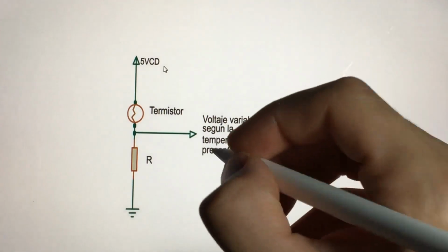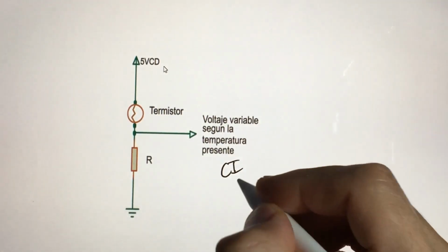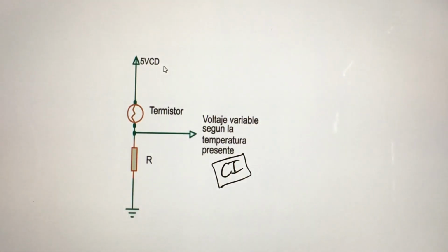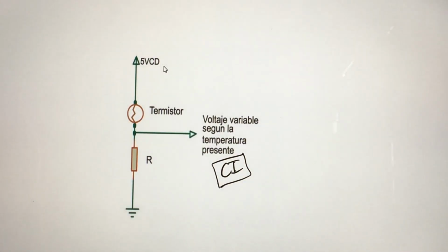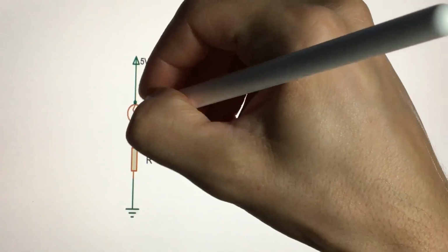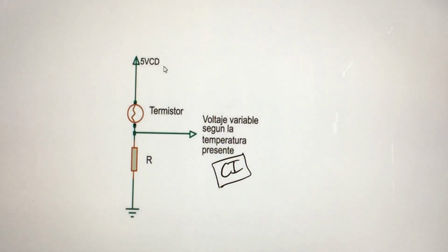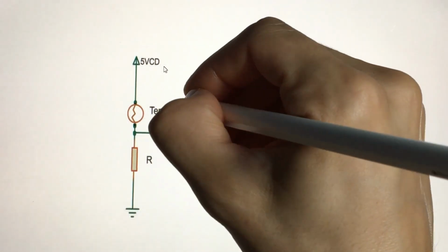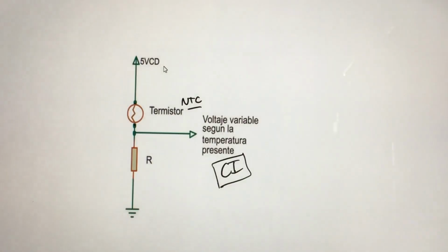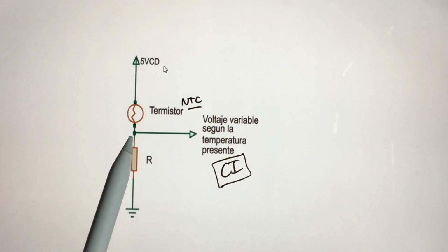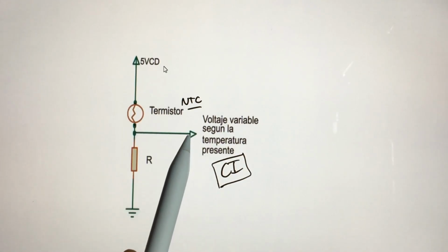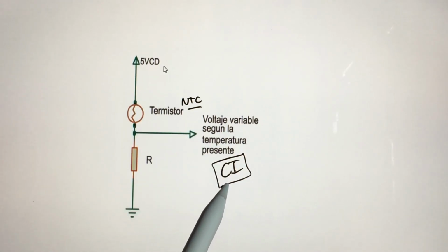What the microprocessor, actually, the integrated circuit, will feel is a voltage variation depending on the resistance of that sensor. In the sample circuit, this represents the NTC, the thermistor or temperature sensor, or NTC variable resistance. So, as this temperature varies, the resistance varies and the resulting voltage that enters the integrated circuit is different.